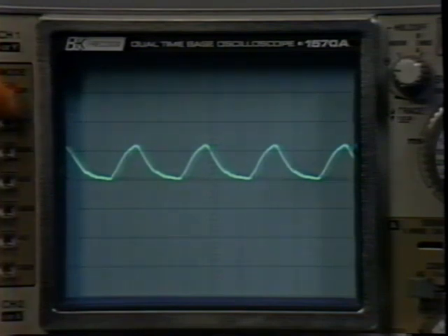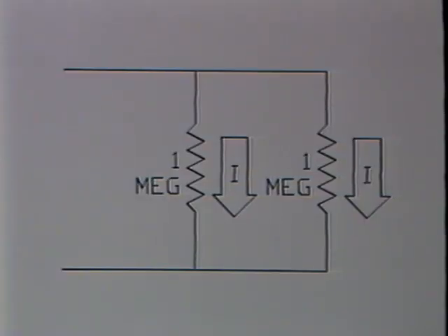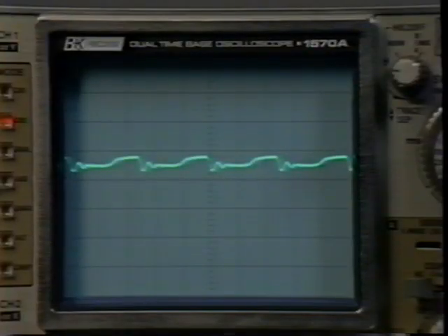The higher the impedance of the test equipment, the less it loads the circuit being measured. Loading the circuit means drawing a part of the circuit's current through the test equipment. In this illustration, the impedance of the scope and the circuit under test are the same, so the scope draws half of the current. This represents sufficient loading to reduce voltage readings and distort the signal. In extreme cases, loading may cause a circuit to cease functioning.